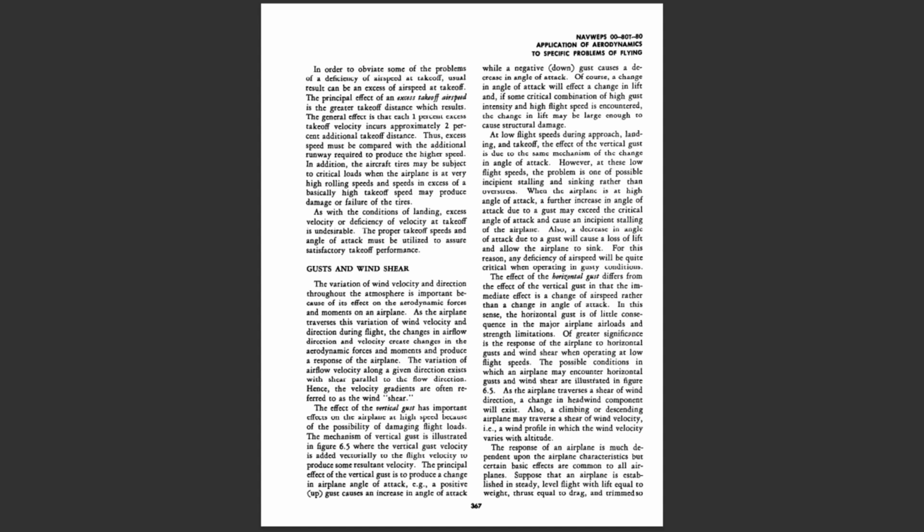In addition, the aircraft tires may be subject to critical loads when the airplane is at very high rolling speeds, and speeds in excess of a basically high takeoff speed may produce damage or failure of the tires. As with the conditions of landing, excess velocity or deficiency of velocity at takeoff is undesirable. The proper takeoff speeds and angle of attack must be utilized to assure satisfactory takeoff performance.